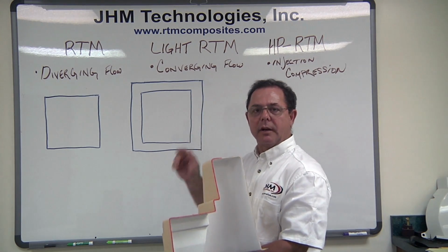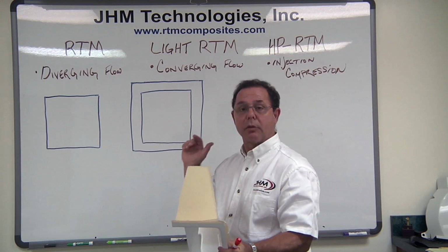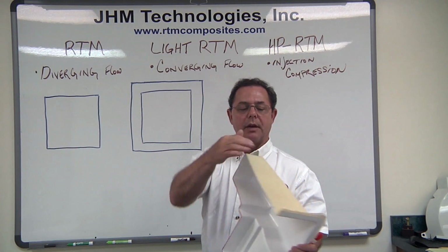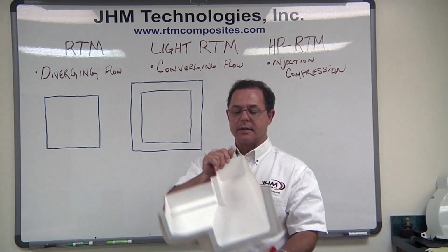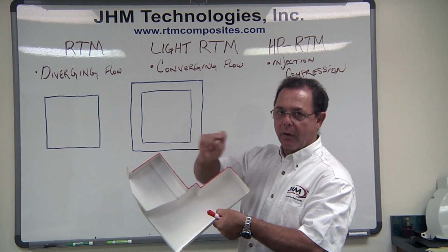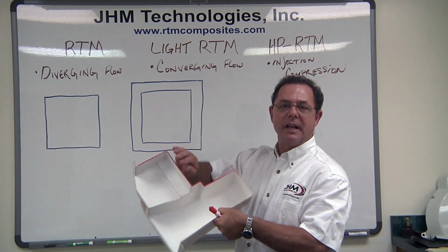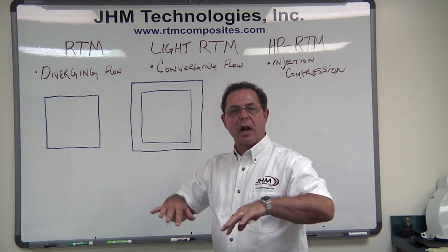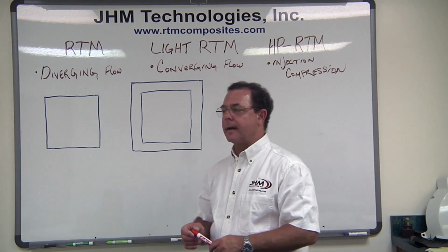But in each of these three examples, there are two sides to the tool, providing for us in each of the three examples smooth surfaces, both inside and out, whether the A side is the outside of the mold or part, or whether it be the inside as it is in this case. The key is that we have a very uniform part thickness, very predictable, based on the part, or based on the mold cavity, and it has finished on each side. Indifferent than that of an open mold, spray up, chop type part, or even a vacuum infused part where we have the rippling on the back side.